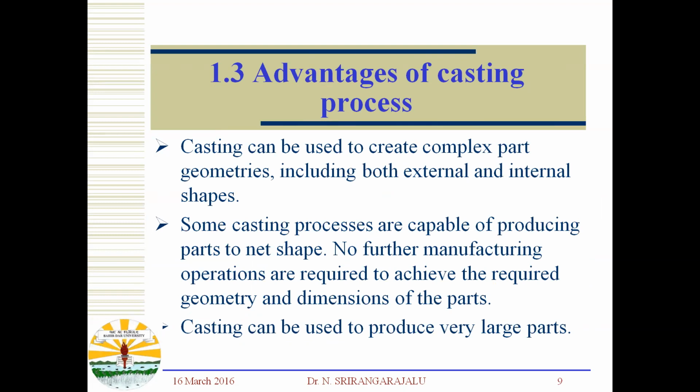Advantages of the casting process: casting can be used to create complex part geometries, including both external and internal shapes. Some casting processes are capable of producing parts to net shape, so no further manufacturing operations are required to achieve the required geometry and dimensions of the part. Casting can also be used to produce very large parts.